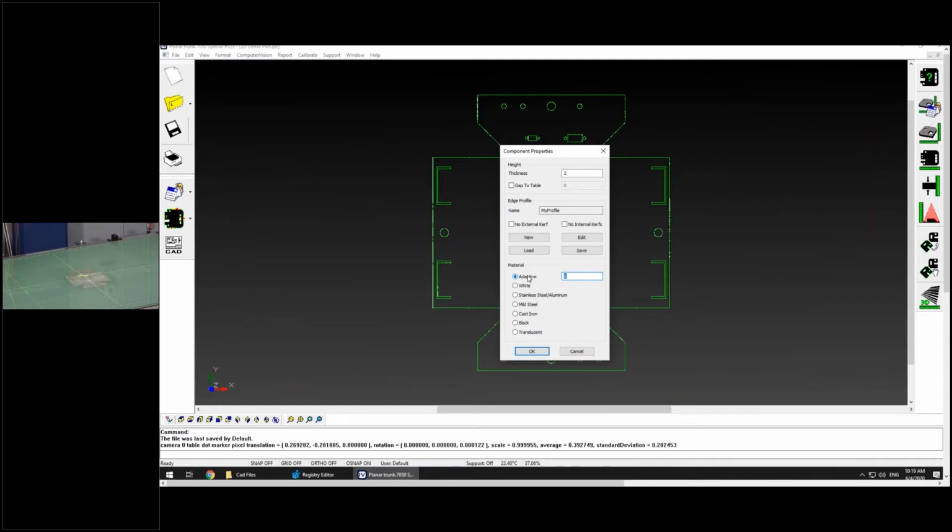Adaptive is a new one that came out in 2019 software, and they didn't really tell us much information about what it is. They just said, when in doubt, why don't you just turn on adaptive and leave it from there? Well, adaptive is basically a way that we can actually adapt the machine to your part. The idea behind this is I'm going to measure this part at a CMM. I'm going to know exactly what the values are on a very highly accurate machine. Then from there, I can come over here and measure it on my machine, and I can see my offsets. I can see, are the overalls measuring long, are the diameters measuring short, vice versa from there.